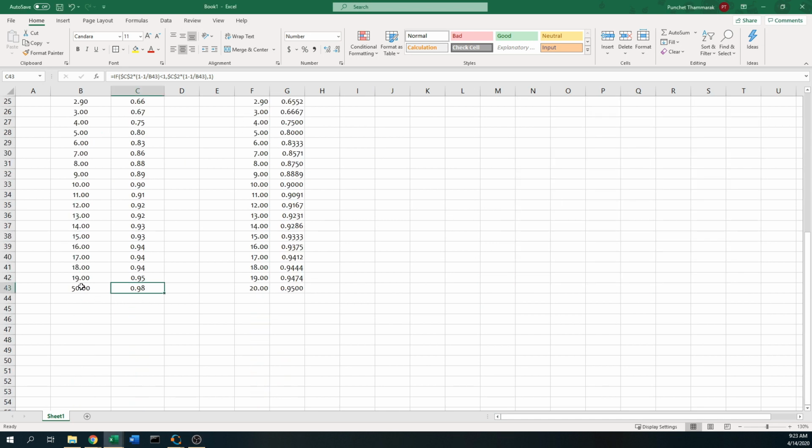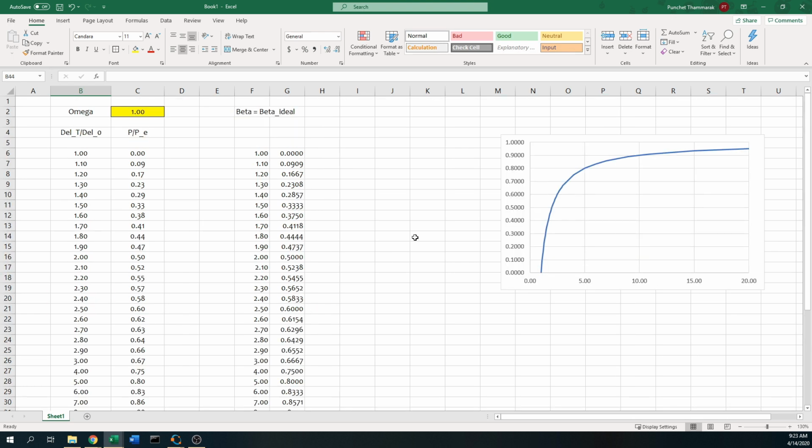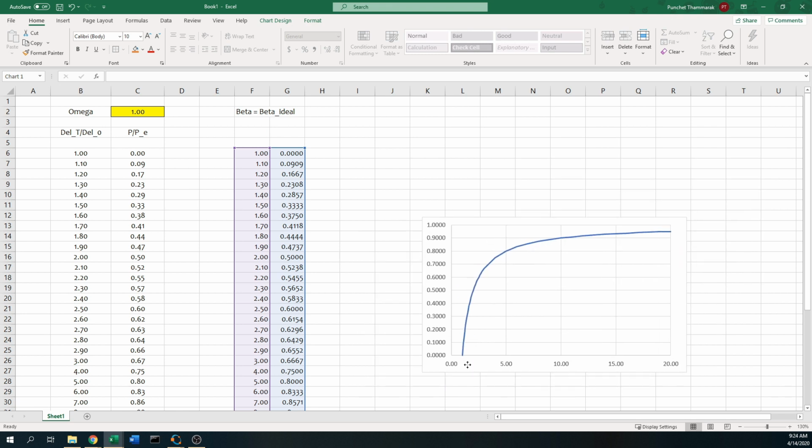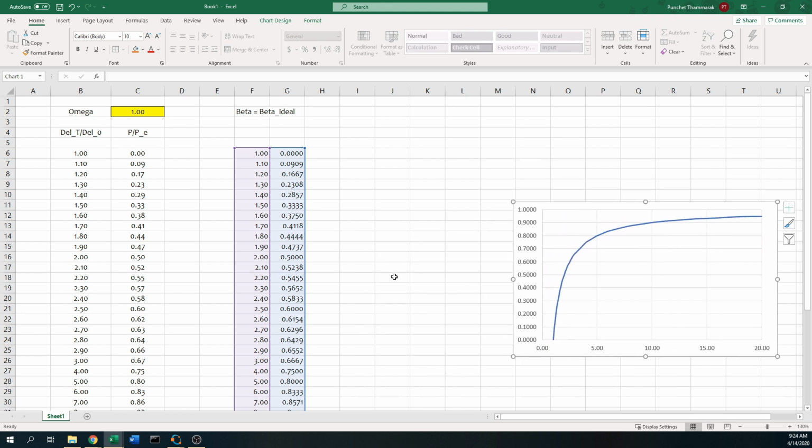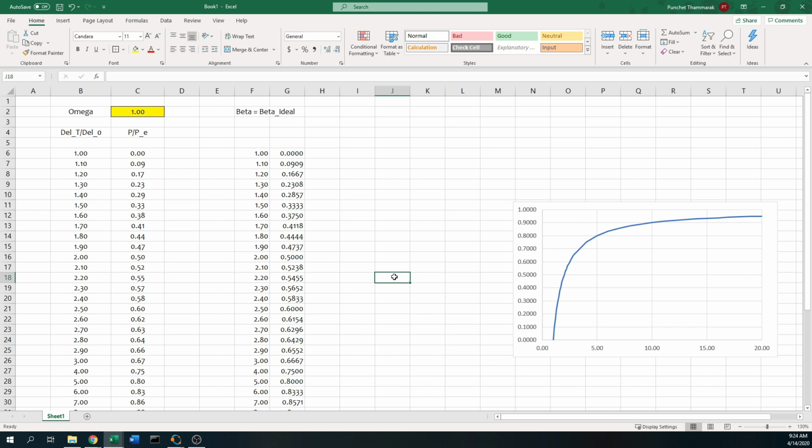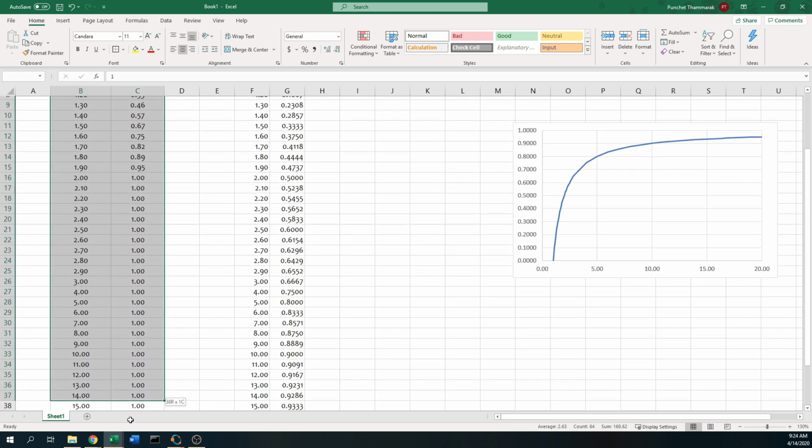The plot here visualizes quite a lot for us. We get a lot of information, and we understand now why this ideal brace stiffness proposed initially is not good for the design, because it just takes too much deformation in order to mobilize the strength. So let's take a look at a brace stiffness which is a little stronger. So we make it 2 times as much. When it turns out to be 2 times as much, this is all we get.